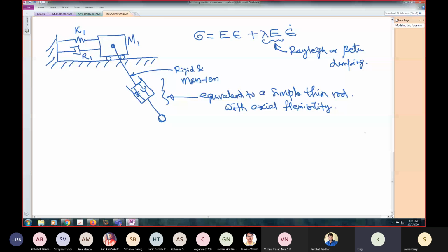So you got a different kind of stress there, but that was at the point of maximum impact. Here we are considering all the intermediate points. Stress is developing, reaching a maximum, again it will come down, again it will reach a maximum and so forth. That is why we have that extra term. This is dynamic stress. So there is another term also, which is lambda times E.